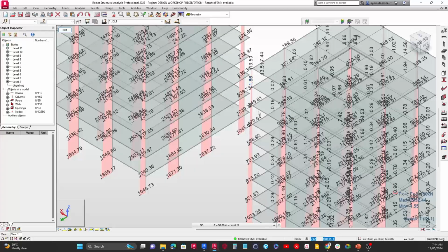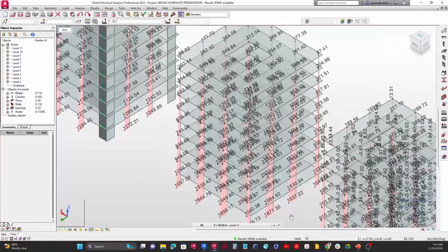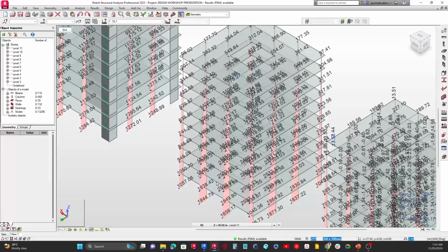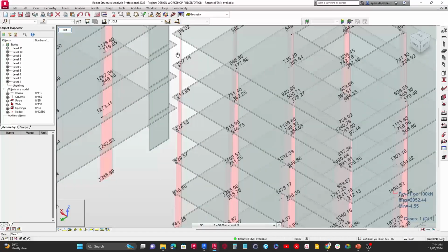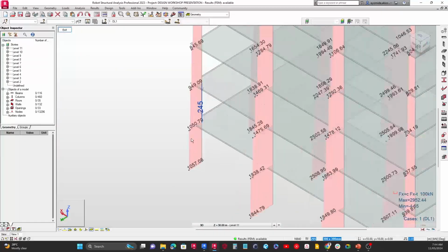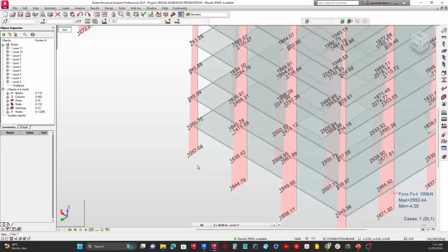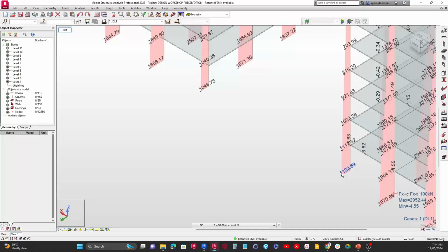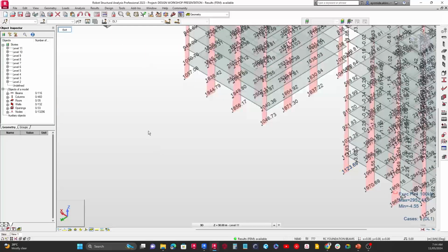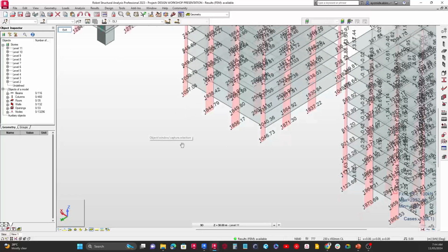We can also see similar behavior in the other structure, but this one here is going to be smaller, right? The values are smaller because we don't have beams, so the loading on this building is smaller. You can see the axial forces here. As we're going from floor to floor, you understand they are increasing, but you can see the last value over here is 1057, compared to this one over here, which is about 1123. That's almost a 100 kilonewton difference, right?